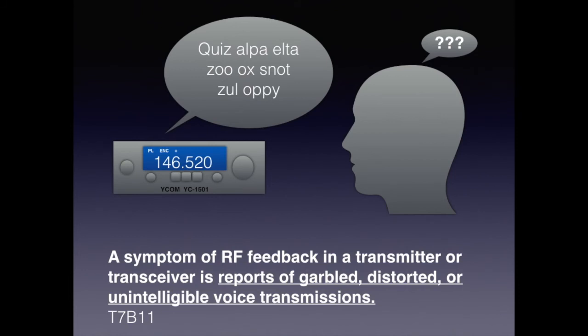Also for the exam, you need to know that a symptom of RF feedback, radio frequency feedback, in a transmitter or a transceiver is you get reports that they're garbled, distorted, or unintelligible voice transmissions.